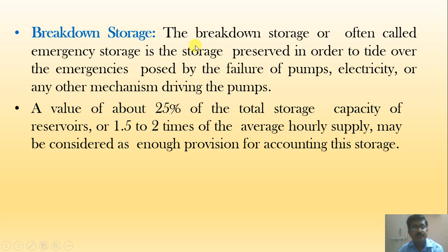Breakdown storage, often called emergency storage, is storage preserved to tide over the emergencies posed by the failure of pumps, electricity and any other mechanism driving the pumps. A value of about 25% of the total storage capacity of the reservoir, or 1.5 to 2 times the average hourly supply, may be considered enough provision for this storage.